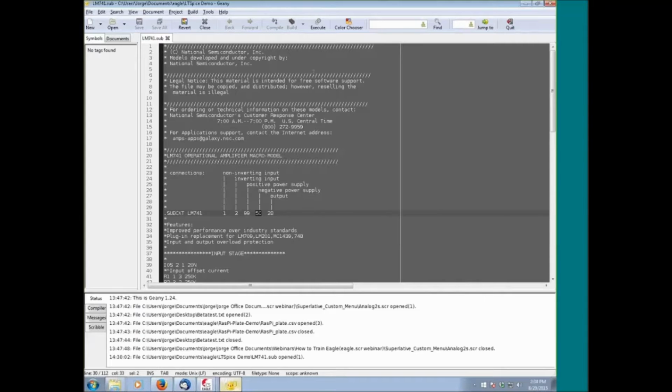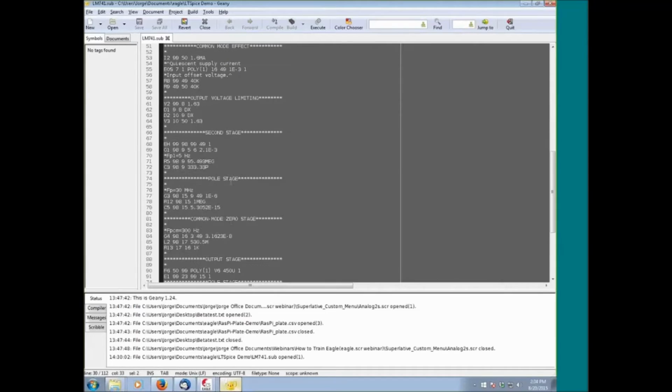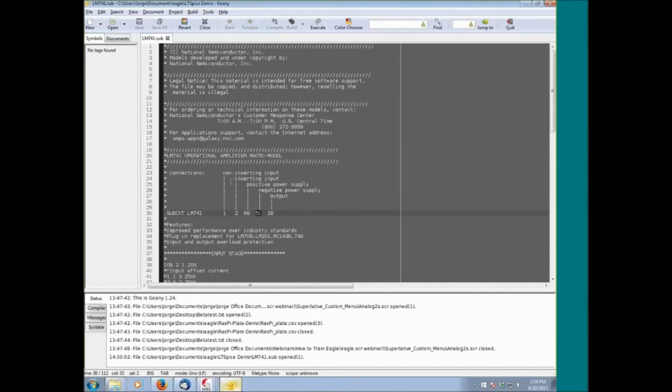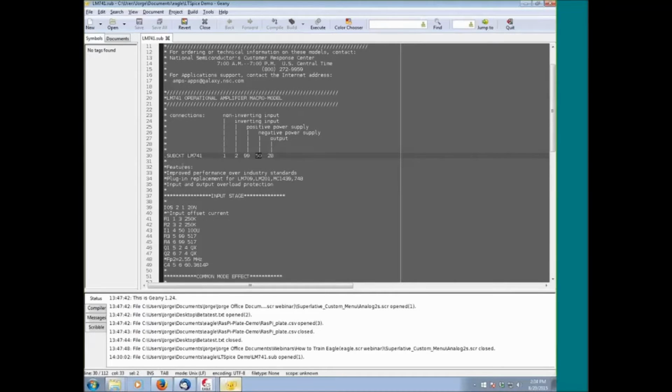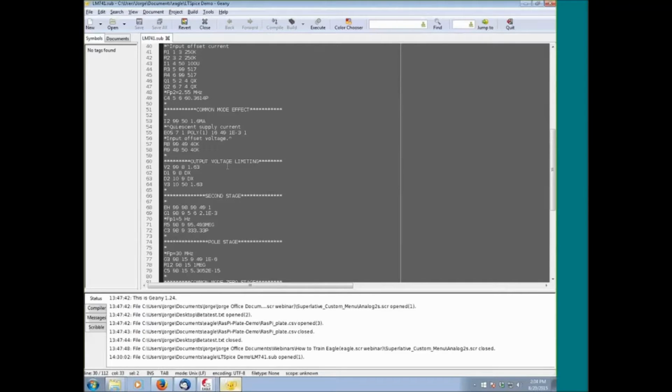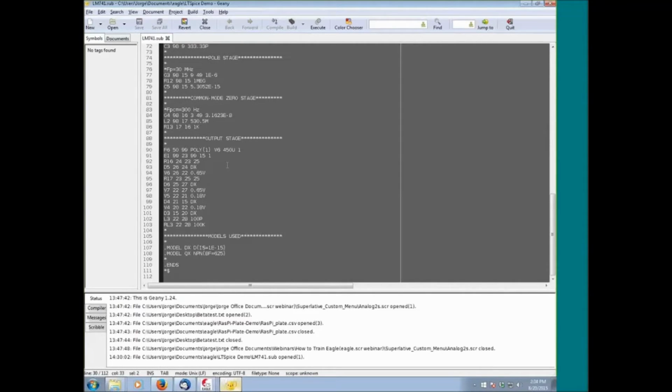That's pretty straightforward. There's no requirement that a SPICE file needs to only have one component, one main model. They can actually be collections of models, and each individual part will be defined by this sub-circuit entry here. And there may be a few other small ones defined.